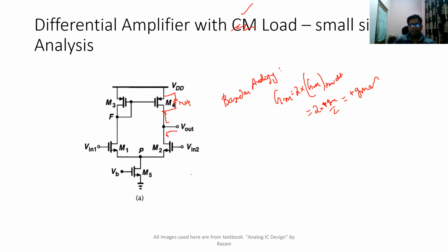This also you can think it to be a fixed bias, because in small signal we will ground small signal, but you know the small signal is associated with the bias voltage also. So if you can treat that bias voltage, it actually acts like a current source. So it also acts like a resistor RO4. Okay, and this node P we have seen earlier in the earlier differential analysis that you can actually ground this node P based on half circuit analogy, based on half circuit concept.